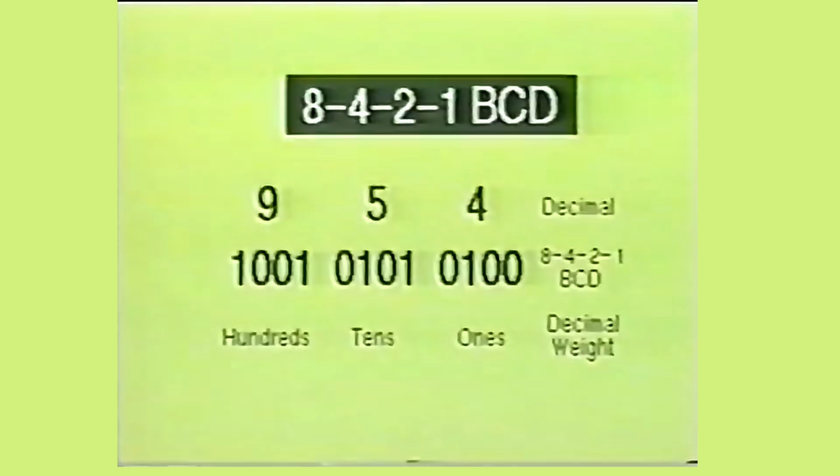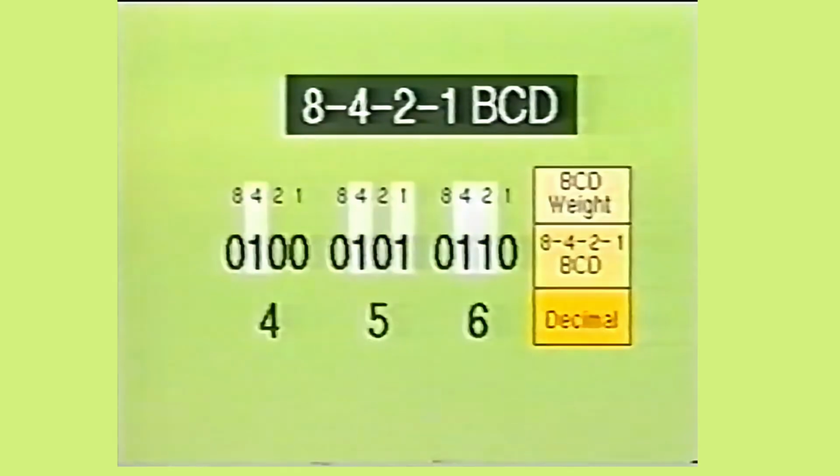The 8421 BCD code is a weighted code in which the weights are 8, 4, 2, and 1. This code is a naturally weighted code because the weights are increasing in powers of the base 2. When encoding decimal numbers into the 8421 BCD code system, it requires as many groups of 4 bits as there are decimal digits. When converting decimal numbers into the 8421 BCD code, you proceed exactly as you would in the hexadecimal system, remembering you do not use the values 10 through 15.